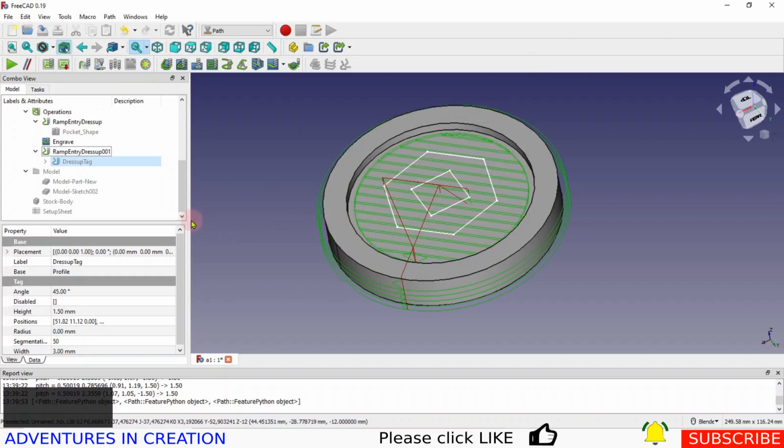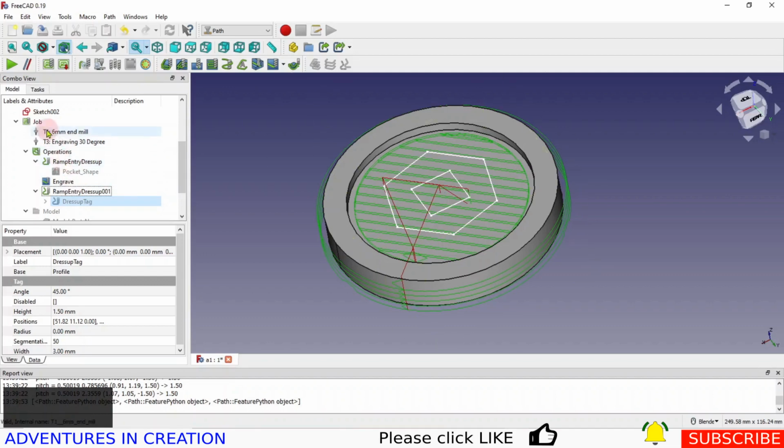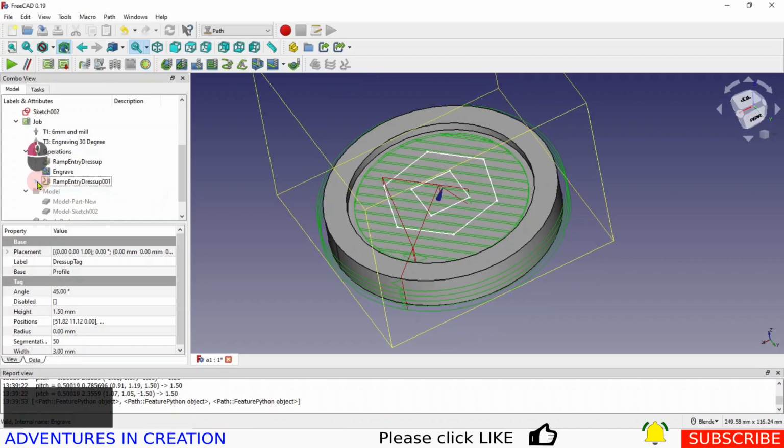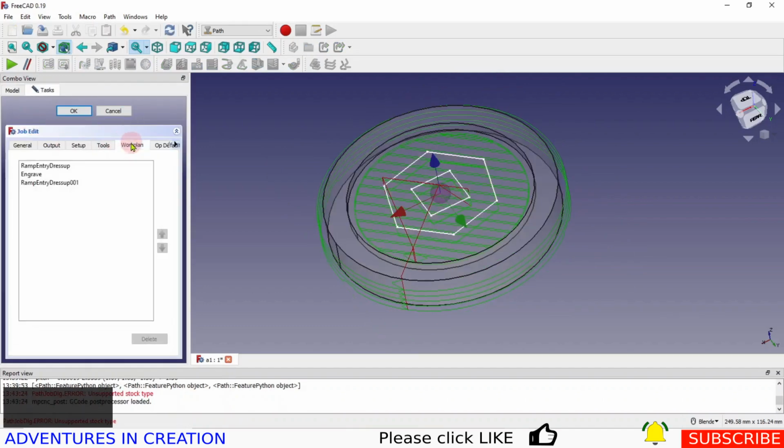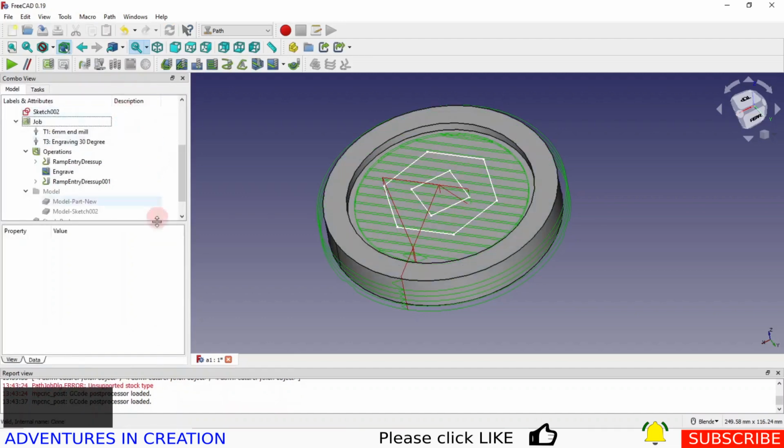One other thing I want to mention is if I wanted to change the order of these things, you can't just pull them up from here. So you don't want to just take that one and put it up above the other one. What you do is you go into the job, you go into the work plan, and here they are. And if you pick on one, you can move it up and down. So you can change the order that things are done. And that's quite easy to do, but you want to do it the right way. Otherwise you can end up in things not working how you expected them to.